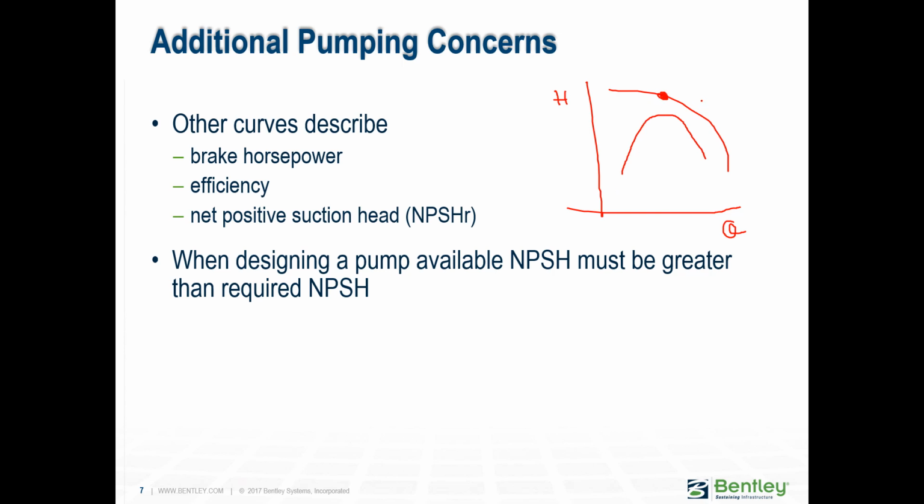So if you just went by your pump curve and your system curve, let's say it said your operating point is going to be right here. But then you see, wow, this is not the most efficient point. Yes, my pump can operate there, but it's not efficient. The problem with operating at a point of poor efficiency is that you're paying a lot in electricity for a pump that's pushing more flow at a lower head than where it's supposed to be operating. So we always want to be kind of on the cusp of the efficiency.